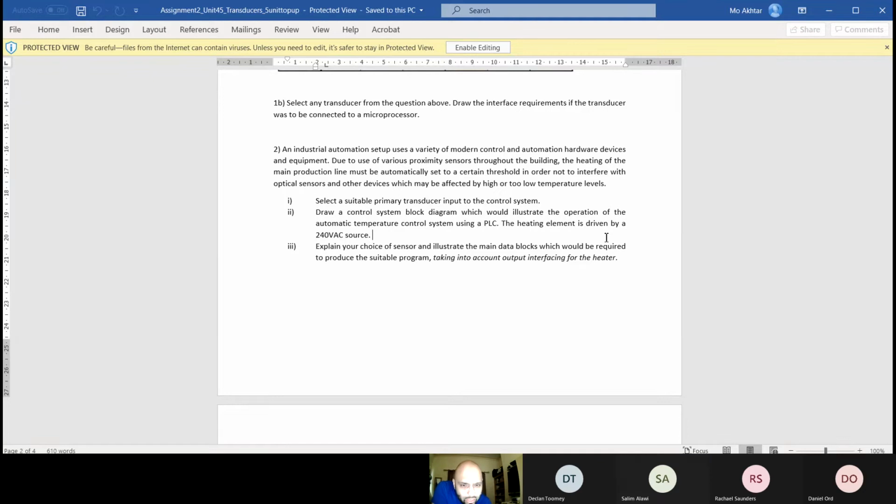But it says here, what was it? Technical account of interface methods for the heater. So you've got the relay for your heater. Now, question: if you're going to have an emergency stop, where should that be placed? The most accessible place. Yeah, but what should it be connected to? The heater. Right, not to the PLC. Why would you not connect an emergency stop to the PLC if you want to switch off the particular output device connected to the PLC?